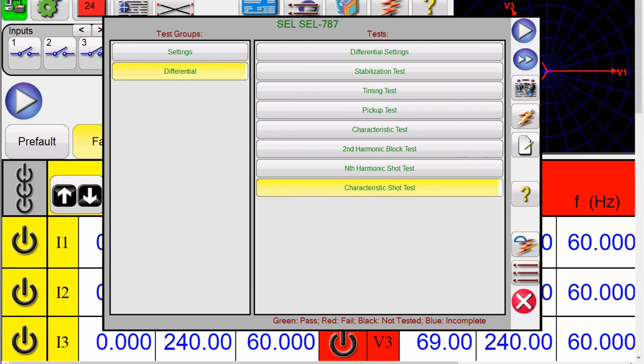So again, the question is, do a study of your protection system, see if your CT is going to be adequate for that application by using the load that you're going to have connected to it and the excitation curve of the CT, and that would be the way to do a proper dimensioning of the CTs that you're going to use in that system.